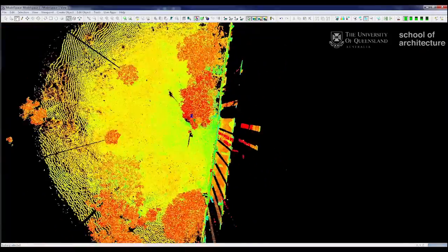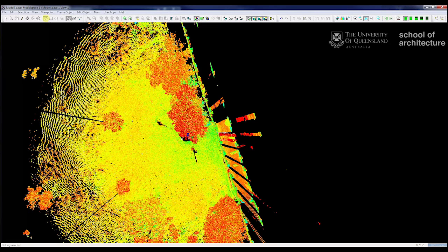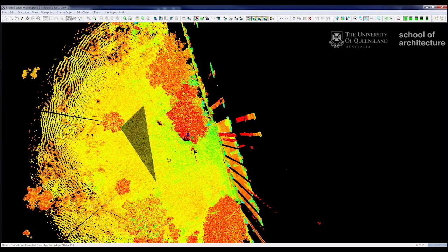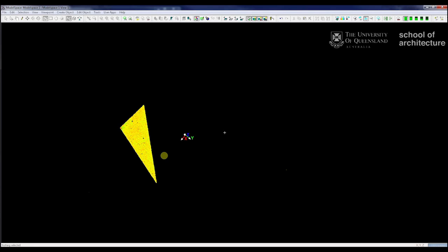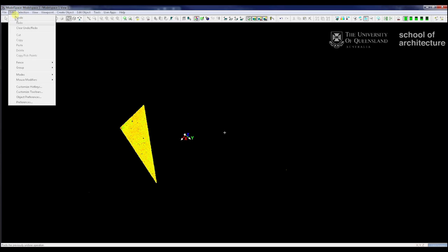Now if I want to highlight something particular, as I showed before, we can create a new model space for inside fence, or I can just add all the data outside the fence. I could delete that. Now remember, of course, as long as you don't close the model space down, everything in here is very reversible through your undo buttons, or of course, Control Z.